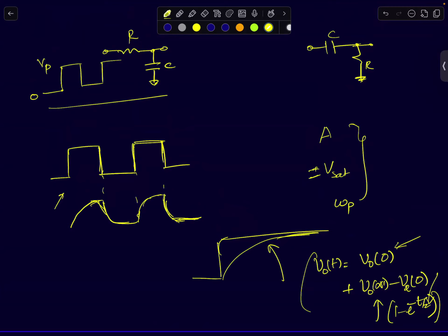So if I feed a pulse input, here there is no steady state output because the input keeps on changing. It goes from 1 to 0, 1 to 0, and so on. And in such a response, your output will also keep oscillating between two values. What I'm interested in is what is the shape of the waveform? How will that shape look? Given I know some relationship between the time period of the signal or the fundamental frequency, let F naught be the fundamental frequency.